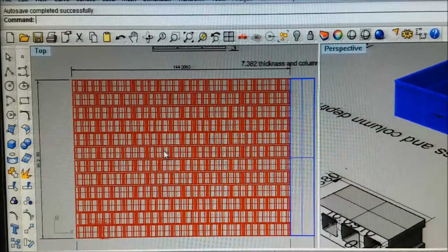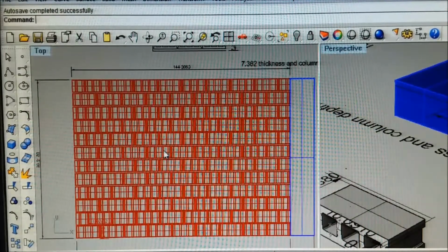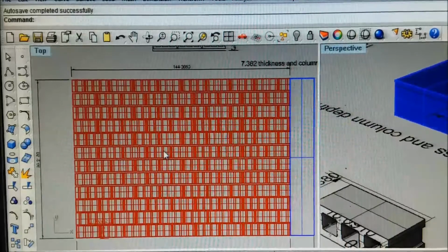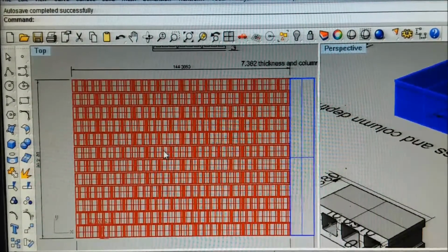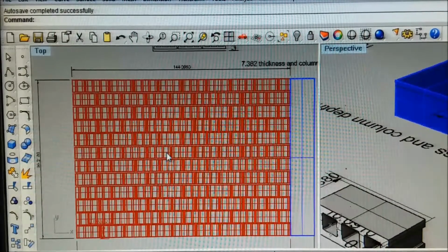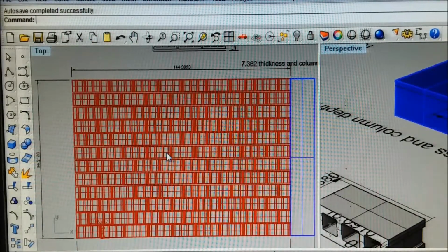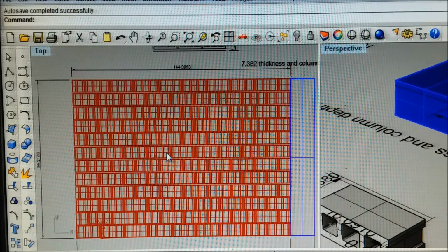Today we're going to do the comparison of a hollow block wall compared to a poured concrete wall. We're going to focus in this video on the materials cost, because the poured concrete is cheaper on labor, but we're going to work on the materials. The method is we're going to figure out the volume of a wall. We're going to figure out the volume of that wall that is hollow blocks, and the remainder of that portion of the wall will be mortar, either between the blocks or filling the cores.